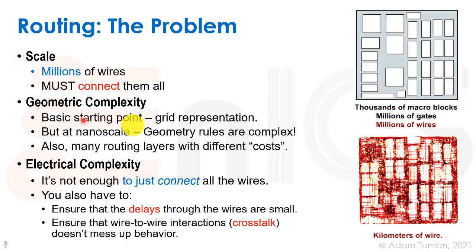So what we do is we take a grid representation, which will simplify things, and then we have to go over and incrementally fix the DRC rules that happen. But what we showed during the lecture is the standard approaches for doing these things with maze routing, and we didn't discuss maybe the detailed route type of fixing the DRCs, but that's just an incremental thing that runs on top of these basic algorithms. It gets pretty complex at nanoscaled technologies where you have hundreds, maybe thousands, of very complex DRC rules, but that's something that can be done if you use your imagination by starting with what we discussed in the lecture.